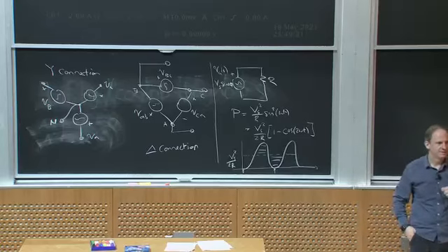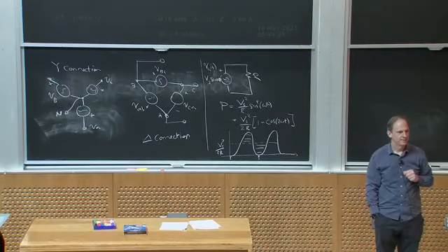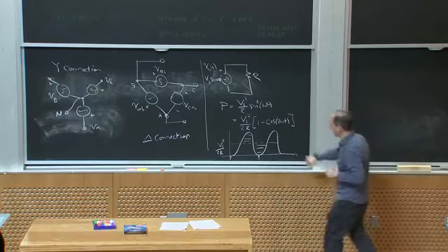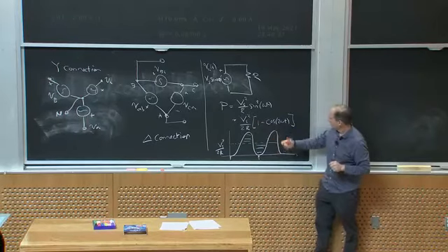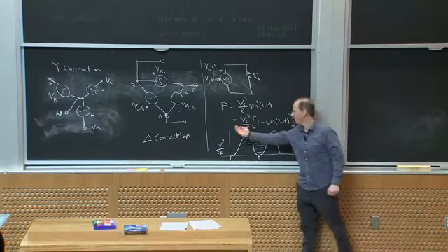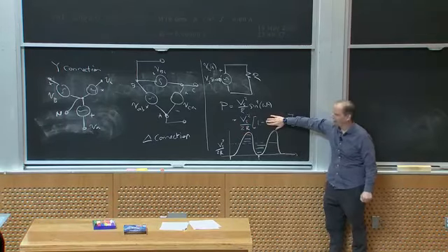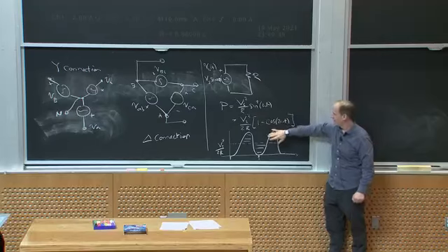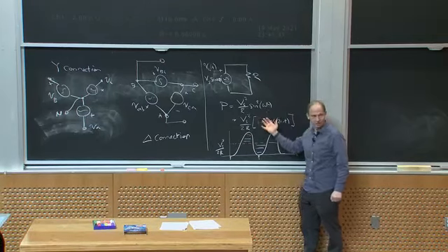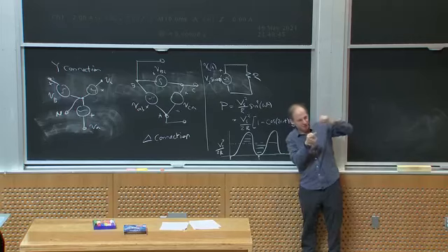So Vs squared over 2R is the average, right? Because the average of the cosine of 2 omega t is 0. If I took a time average of this, this term goes away and I get Vs squared over 2R. And then I get this equal-size pulsation, so the peak pulsation is equal to the average value.